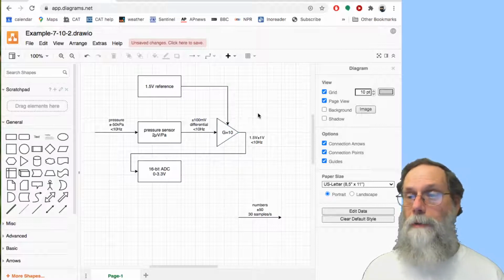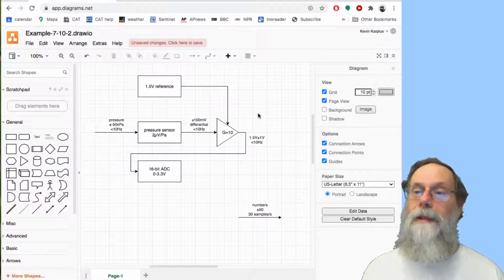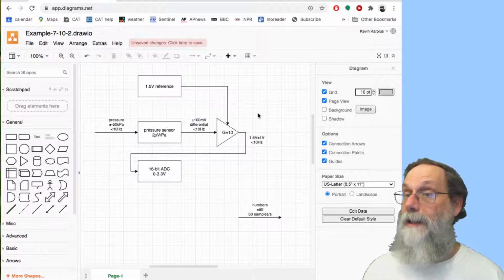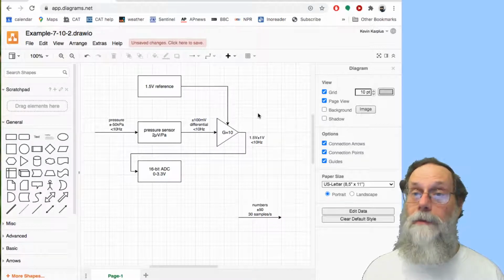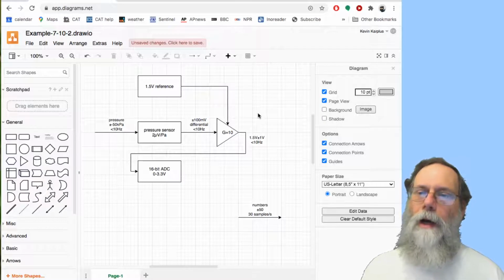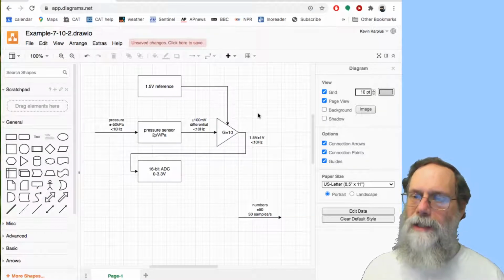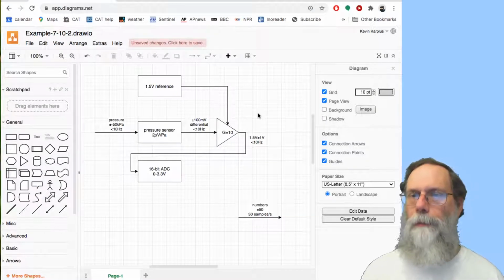Sometimes they're done in block diagrams, sometimes not, depending whether or not they vary in different parts of the block diagram. If you have different blocks with different power supplies, then it becomes very important to indicate which power supplies go to which blocks. If it's all on the same power supply, then the power supply may be omitted. Depends on the purpose of the block diagram. What part of the design are you trying to summarize here?